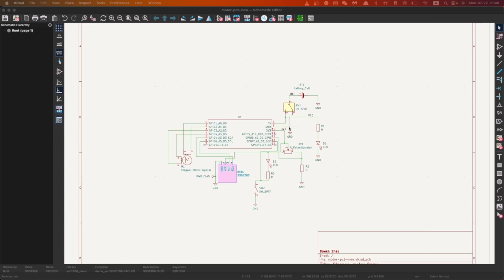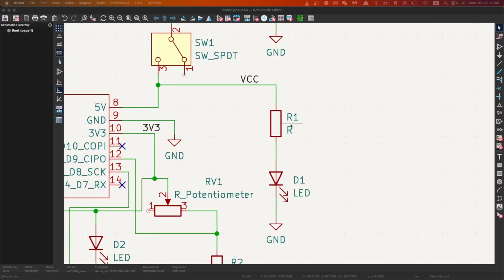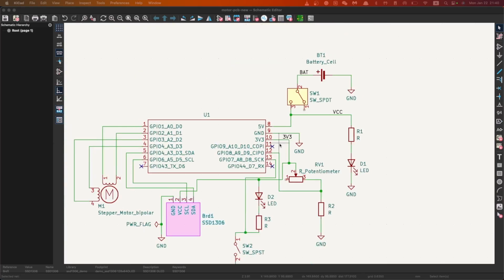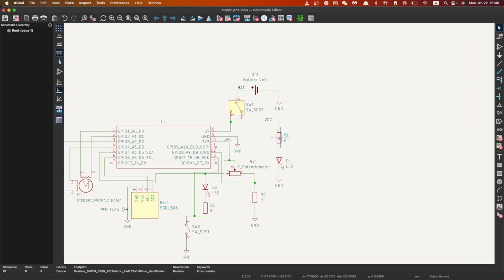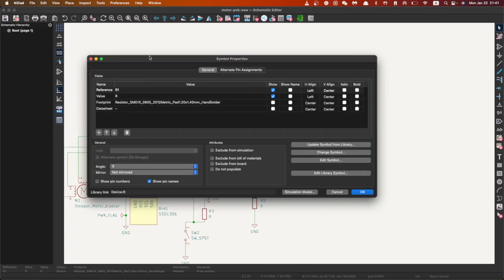So as we see here, there are resistors on your circuit, but the problem is their resistance values are not being filled. So that's what I want to do next. For each component on your circuit, you can edit their characteristics in KiCAD's schematic editor. As I'm saying that you can edit it, you might guess that the shortcut for it is E. So click this component, press E, and a simple properties window will show up.